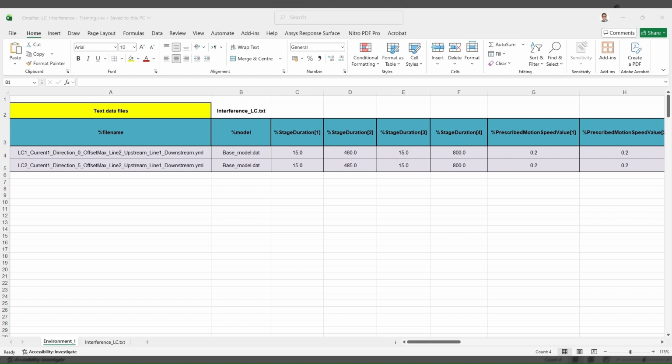The second point is related to buoyancy module modeling. If VIV analysis is performed before the interference analysis in order to obtain drag amplification factors, the buoyancy modules should be modeled discretely, not as a continuous or smeared buoyancy section.